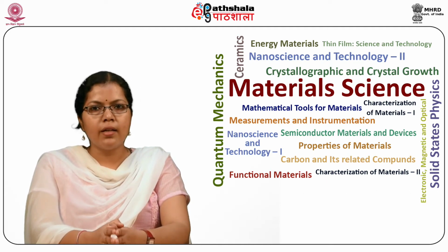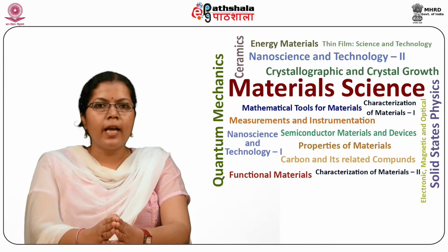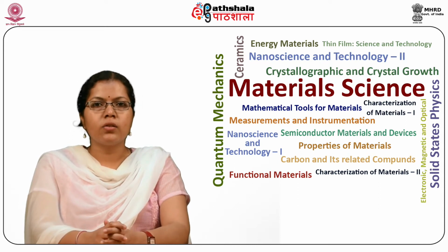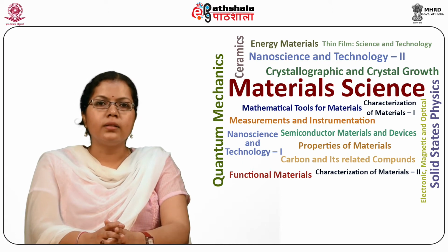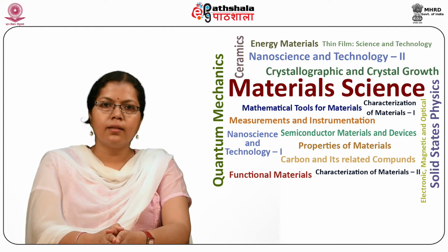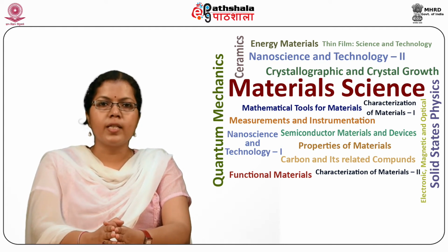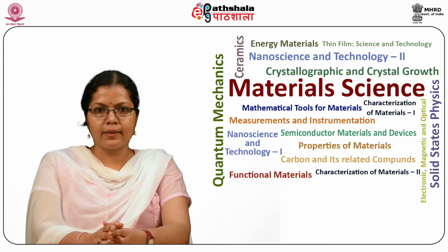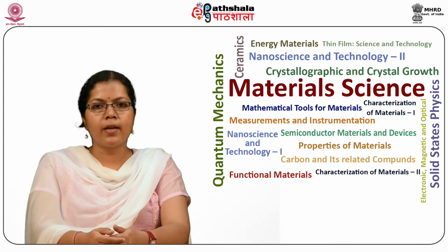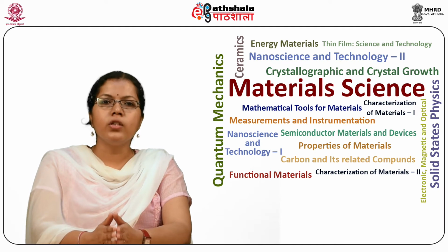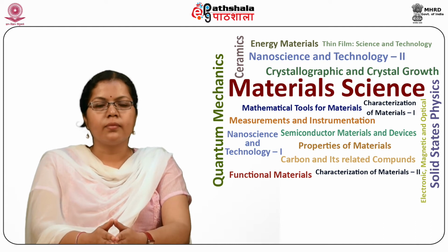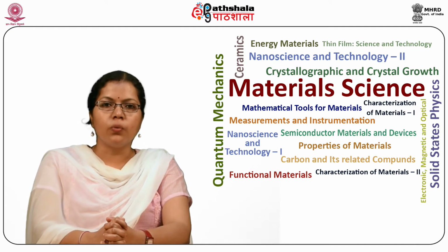When incident radiant energy falls on the cathode plate, electrons are emitted from its surface and are collected by the plate or anode. The current through the photocell depends on, first, the intensity of light, second, the wavelength of the light, third, the voltage applied across the cathode and the plate. Photocurrent response of the vacuum phototubes is linear over a wide range, so much so that they are often used as standard in light comparison measurements. This linear relationship is shown in the figure.